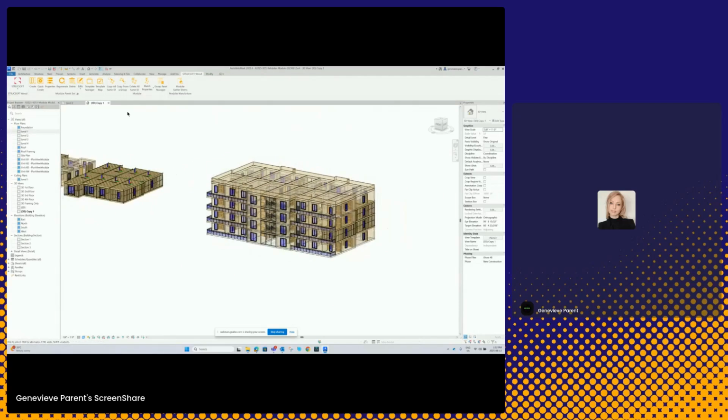Okay. When it comes to the delete all same with ID, we're just going to hover over this. I find these little descriptions very, very handy. Deletes framing in identical model groups. Use this tool by first selecting a group of walls containing panels. Then select the tool. This will delete the framing contained within all duplicate wall groups.